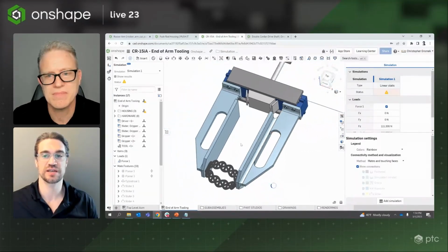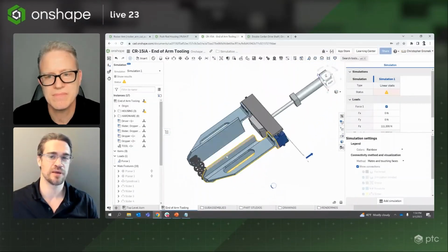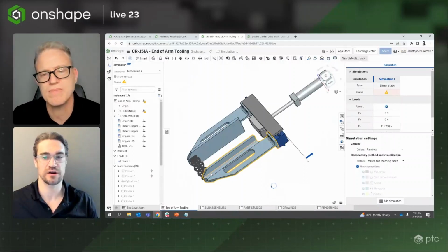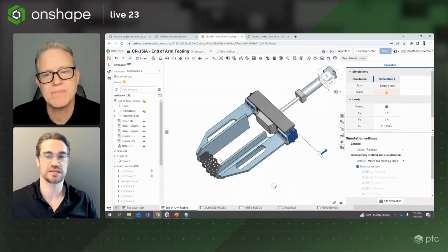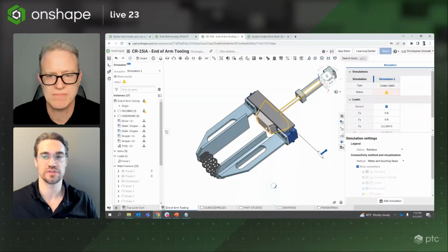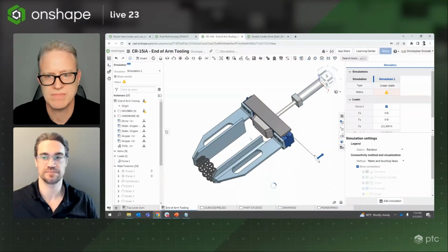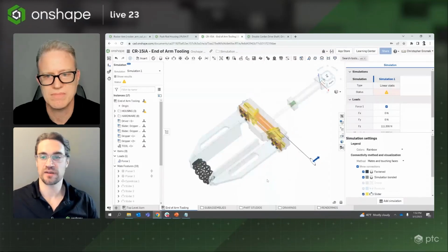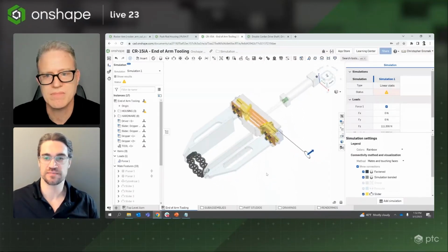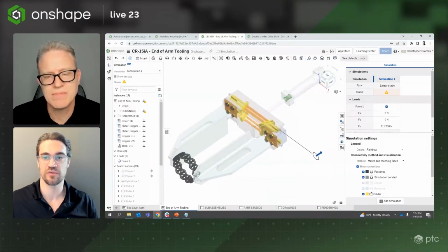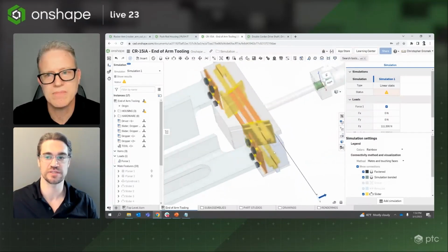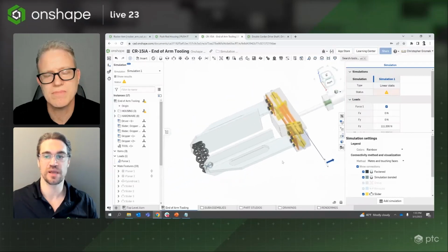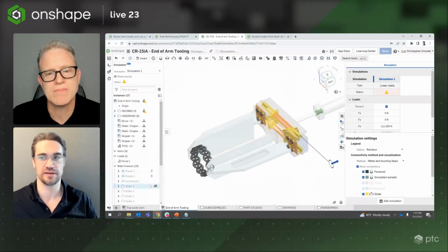And Onshape simulation, again, is going to infer that the gripper fingers here and the ring tooling here are going to be stuck together as we drive this driver here on the plunger side. Now, I've hidden a couple other inferences. All right. I've got standard content in the form of these 8 bolts, and those 2 have connections inferred with the sliders here. All of my other mates, though, are respected as I've defined.